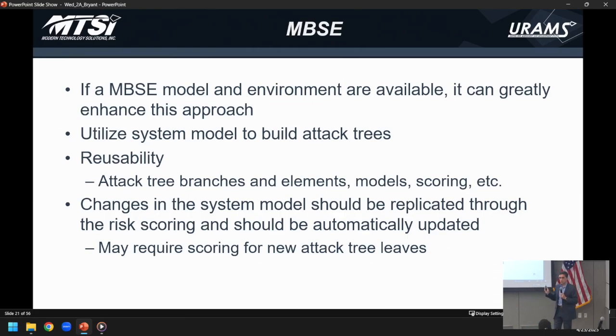And so what we've done is we've taken this example, the MQ-99 Berserker, and we've built out a complete set of attack trees within an MBSE environment. The reason why that's important is that these quickly get out of hand. On this conceptual level UAS, there are about 350 nodes in all of the attack trees. If you're trying to track that in PowerPoint, good luck. But within an MBSE environment, it becomes much more doable because it's tied to the actual structural, architectural, and mission models that you have in the system.